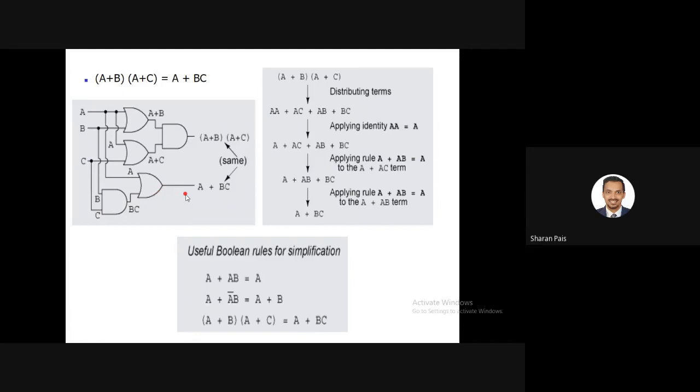So you may think how much it may cost us to have one more logic gate. Because we have in IC there are four. I can use the circuit whatever I have in the three logic gates. We can use it. Yes, we can use. But the problem is each logic gate, it is a physical component. There is some transistors, all those things will be there in the IC. So each component will be having its own delay. Some error factor, some leakage current, voltage, all those things, then the error factor will be there. So those delays will be having impact.